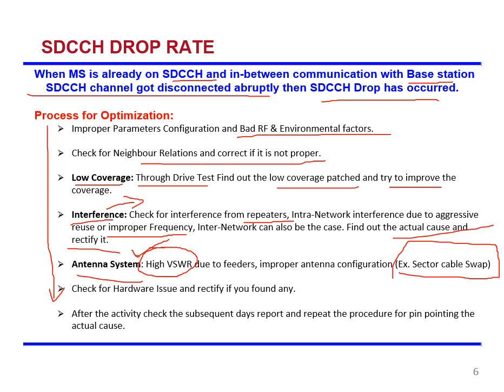You attend the faults. Maybe any bird nests are there at the antennas. Clean the antennas. Change the connectors. If any bends or breaks are there in the RF cables, you have to verify them and attend antenna faults. So thereby this can be attended. And check for hardware issues and rectify if any are found.